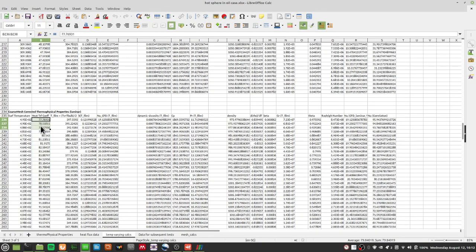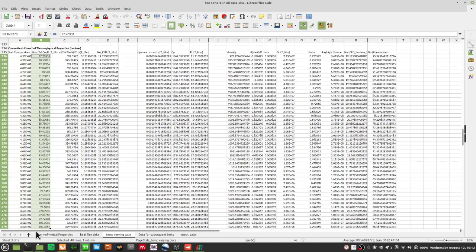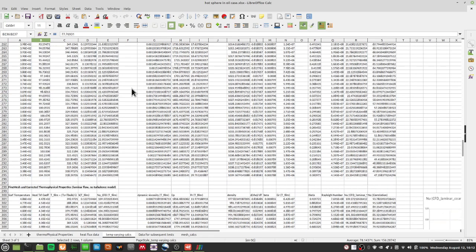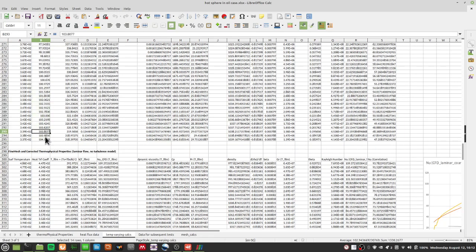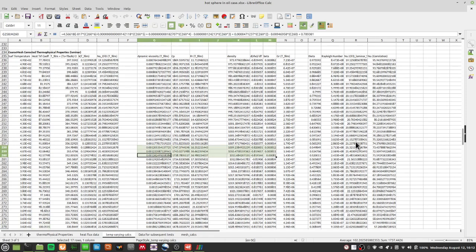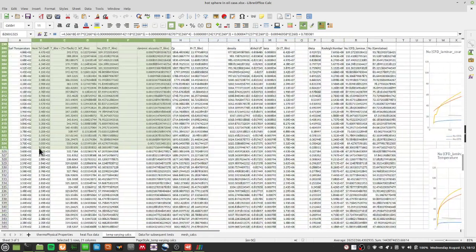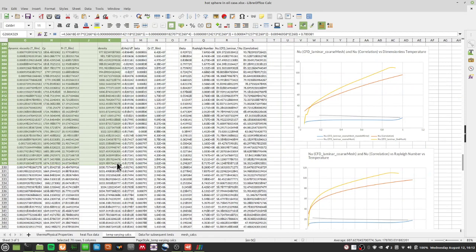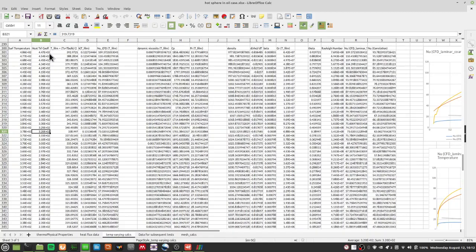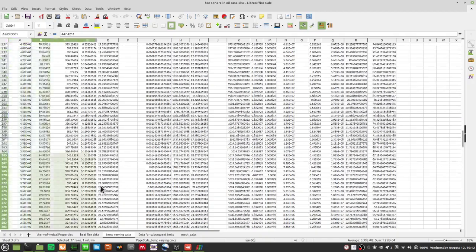We take a look at a thermophysical property, the laminar case. We also realize it's actually somewhat higher than what we get over here in the laminar case. So this turbulence modeling does help a little bit in terms of increasing the heat transfer coefficient. However, it does not perform as well as the fine mesh with laminar calculations.